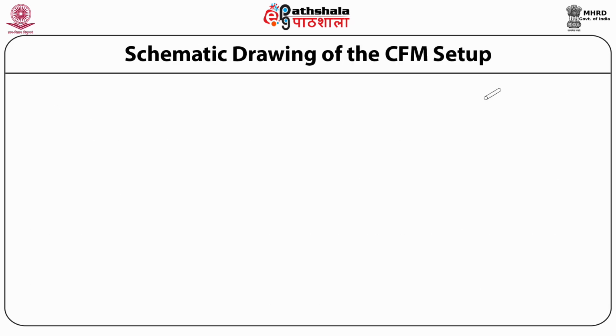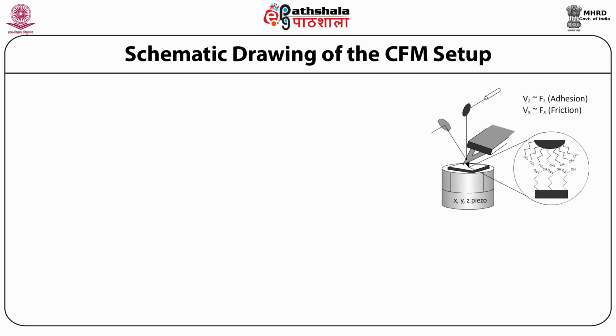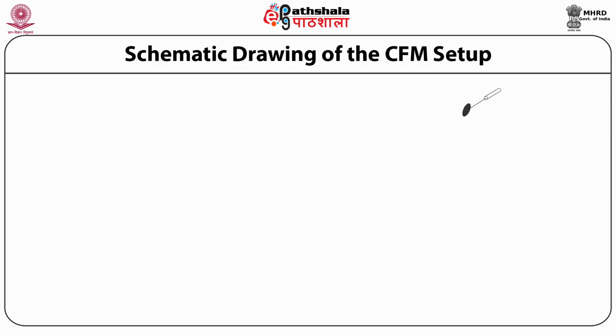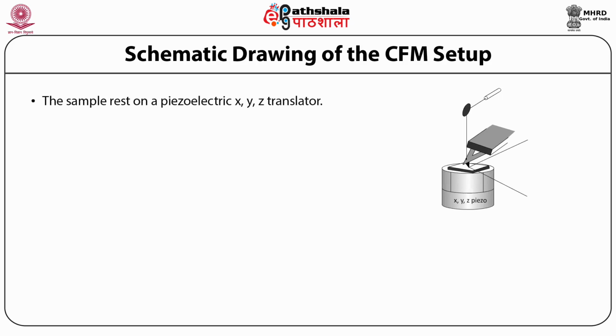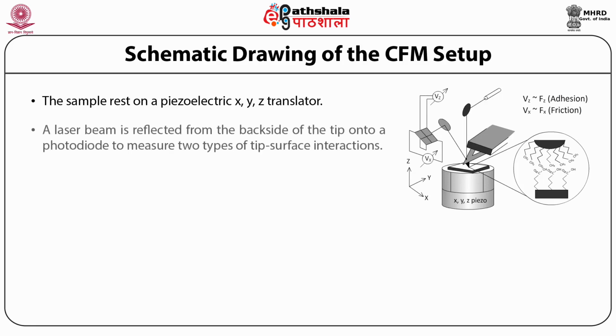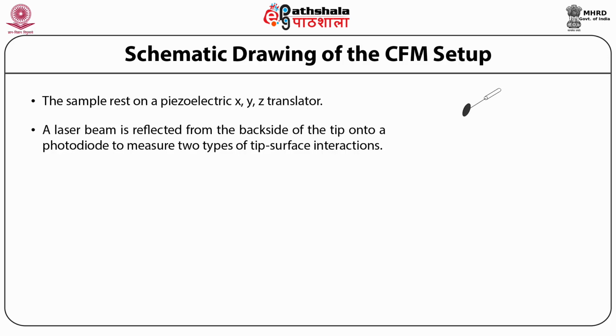This gives a schematic diagram or drawing of the CFM setup, that is, the setup of chemical force microscopy. This has been shown in the diagram and it indicates the way it works. The sample rests on a piezoelectric XYZ translator. A laser beam is reflected from the backside of the tip onto the photodiode to measure two types of tip surface